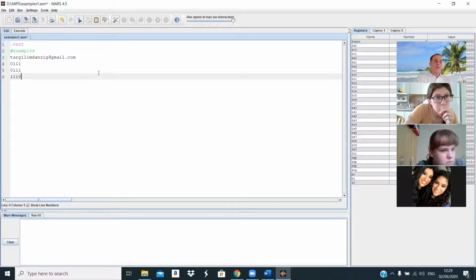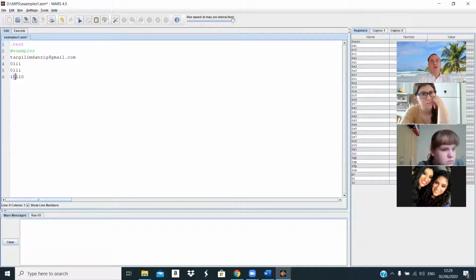That's the result. Now, notice that the sign bit, which is the 0, got destroyed. That's always what's going to happen in addition. Nothing else. In other words, you'll never get 2 numbers that are in 4 digits, and the result will be, let's say, like this. Let's say theoretically, I added 2 numbers, and I got a result that was not 4 digits, but 5 digits. And it happened to be that it was a 0 over here. And then when I look at that digit, I see, oh, it's a 0. So it's still a positive number, so I didn't have an overflow.